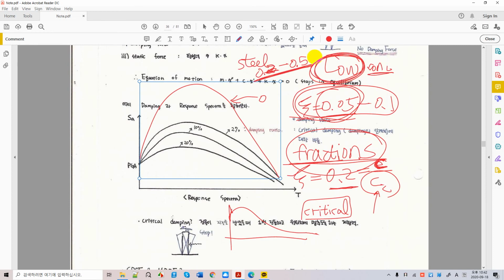For a high-rise building, your damping is really small, like 1% to 1.5%. Don't forget. Okay, let me just say it again. You're having a low-rise building. It is different for these two cases, concrete building and steel building. You have probably 5% to 10%, maybe a little over 10% for a concrete or low-rise building, and 2% to 5%.